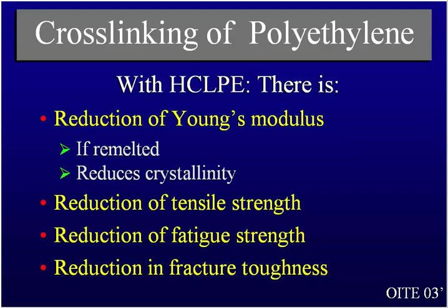Remember that the reduction of Young's modulus and all those properties occurs when you remelt it. If you remelt it, then you get more cross-linking, you have less crystallinity, you change the mechanical properties. It's the crystalline areas that keep the fracture toughness, but if you decrease the crystallinity to increase the cross-linking, then you have diminished mechanical properties. Okay? So a highly cross-linked polyethylene is not stronger, it's just more cross-linked, which gives you better wear rates. Okay? Do you understand that? Highly cross-linked products are weaker overall, but wear better.